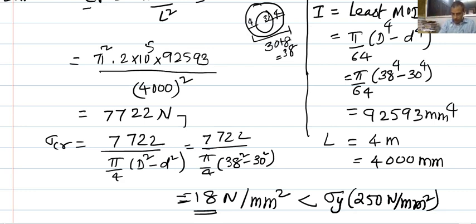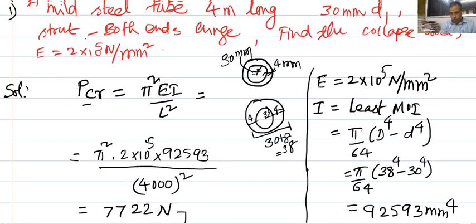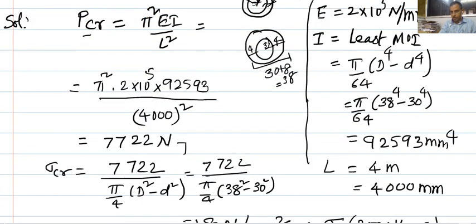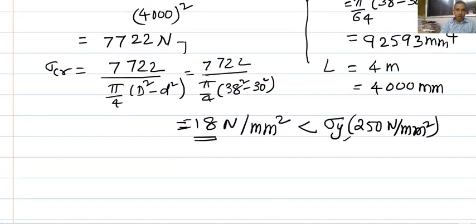So, this part you can verify, otherwise the cross section may be too high, your yielding may be early, but anyway in this question there is nothing to worry, because it is very clearly told it is collapse. So, collapse we call only for buckling. When you say collapse, it means it is for the buckling only. Okay, is this clear?